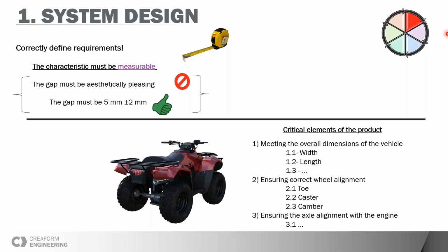DM is part of that whole communication, and GD&T is part of that whole communication, where you say, well, maybe it's true, maybe the guy on the production line is right, this doesn't make any sense, so you should change what's on the drawing. But on a jet engine, most probably the engineer who put the tolerance knows what he's doing, and he's tested the engine before, so they know you need to be within that specific tolerance.